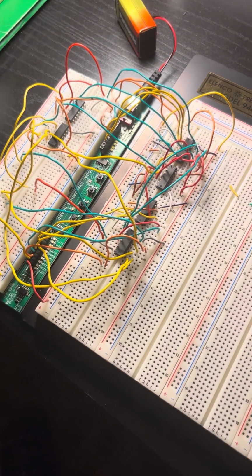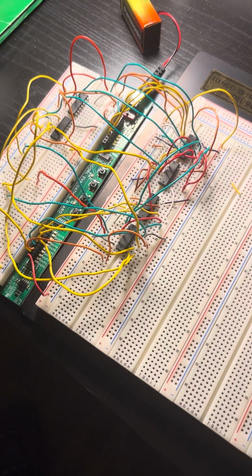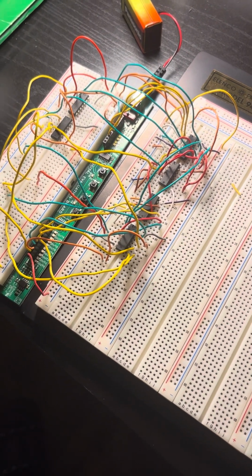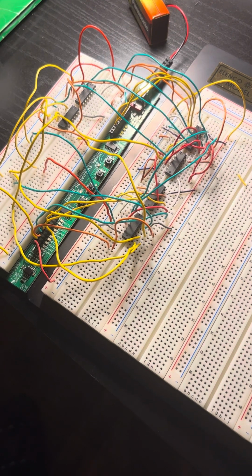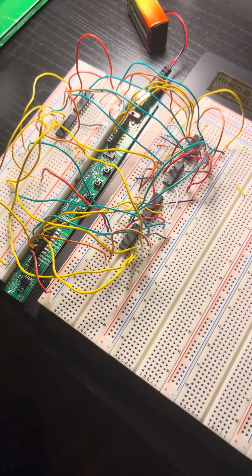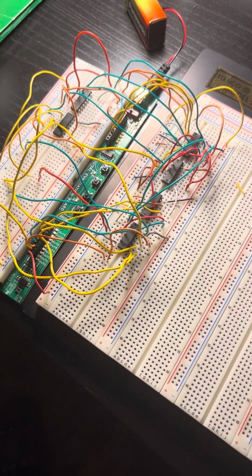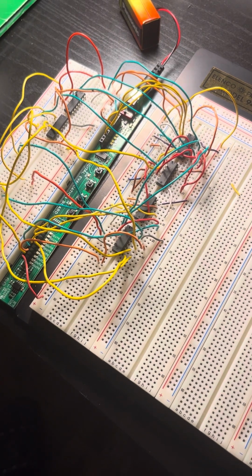Okay, so here's my hardware implementation of my read-only memory that displays the 7-bit ASCII code for each character in a 6-letter word. Now the word that I chose to use was endure, with all capital letters. And since there are 8 possible addresses when using a 3 to 8 decoder, I also chose to add 2 underscores as my last 2 characters.